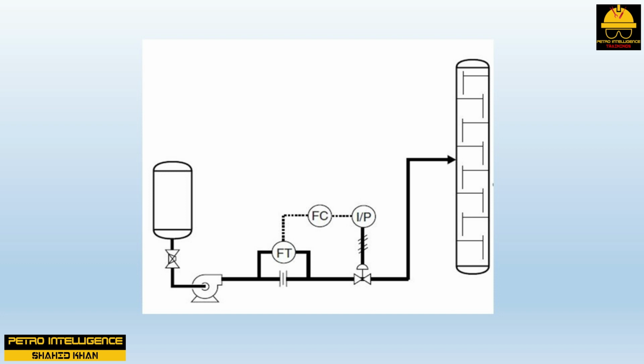Orifice plates create a pressure differential that can be measured by a DP transmitter. Primary elements are typically used in conjunction with a transmitter. Although it appears that the primary element is interrupting the flow, it is not. Increased velocity across the orifice plate compensates for the restriction. The transmitted signal is sent to a controller that compares the incoming signal with the desired set point. If a change is required, the controller will send a signal to a final control element.